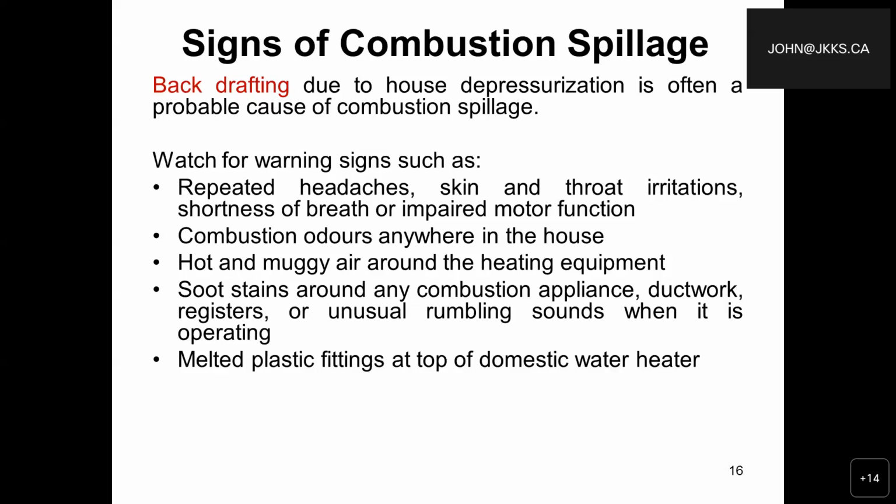So there are specific or certain types of appliances within the house. For example, in our house, we have what they call the Gen Air cooktop. It has a very powerful fan on it. And it can, in some homes, under certain conditions, cause backdrafting just by putting that Gen Air cooktop on. So in other words, the old way it used to snuff out the pilot light on the water heater. So again, signs that problems are brewing.